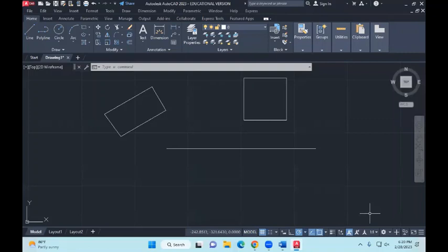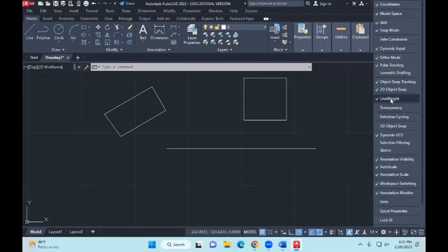Okay, there's one button by default, except for my case, in all of your PCs, it will not be showing by default. So what I'd like you to do is go to the bottom right hand corner and find where it says line weight and make it display that button. Right. So just give me a bit of a challenge. Find where line weight is. Go to the bottom right hand corner, line weight.